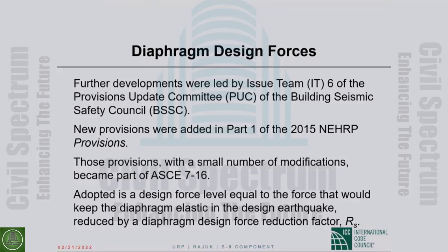I do not know why that would cause confusion. This is like shear wall boundary elements. That does not require a thickened shear wall end. You can have a rectangular wall with specially confined boundary elements detailed within the thickness of the wall. It is the same thing. You can have beams, which are fine. They will act as collectors. If you don't have beams physically sticking below your slab, you can have just a bunch of reinforcing bars acting as collectors. Both ways is totally fine, and both are very common.